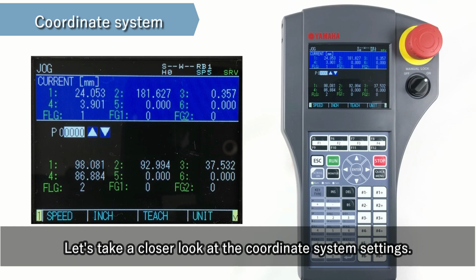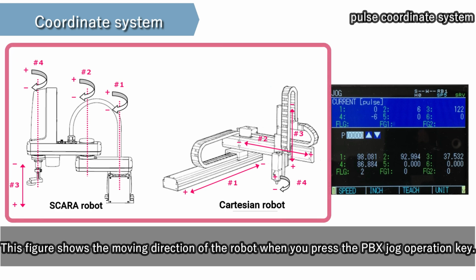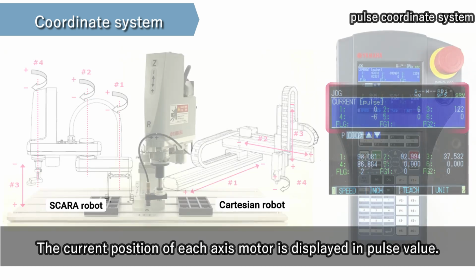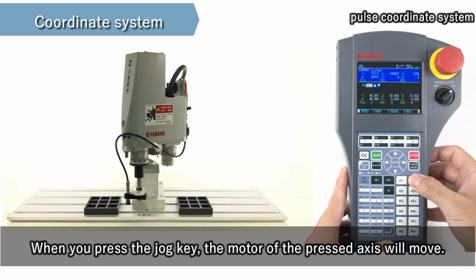Let's take a closer look at the coordinate system settings. First is the pulse coordinate system. This figure shows the moving direction of the robot when you press the PBX jog operation key. The current position of each axis motor is displayed in pulse value. When you press the jog key, the motor of the pressed axis will move.